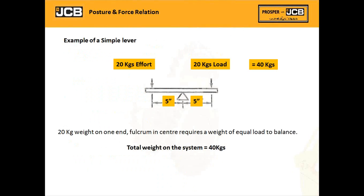Now let us consider one more example, that is, the example of a simple lever. See, if this is a lever and this is a fulcrum, and the fulcrum is at the center, and if we have to balance the 20 kg weight over here, simply if it is in the center, we need to put a 20 kg weight or a 20 kg effort, and you can easily balance the lever. So that means in this case only 40 kgs of weight is coming on the system.